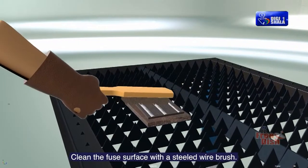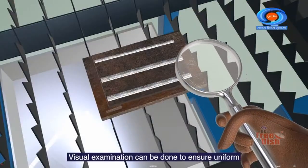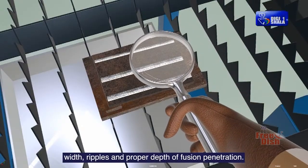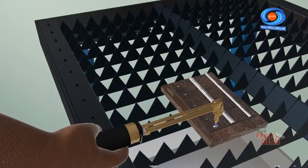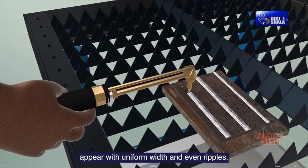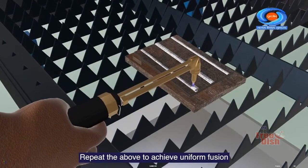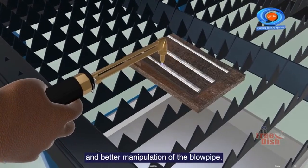Clean the fusion surface with a steel wire brush. Visual examination can be done to ensure uniform width, ripples and proper depth of fusion penetration. If the speed of travel and blowpipe motion are correct, the fusion runs will appear with uniform width and even ripples. Repeat the above to achieve uniform fusion and better manipulation of the blowpipe.